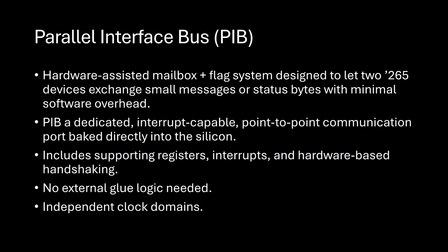Now with this, you should not need any external glue logic. You can have the 2 different microcontrollers on totally different clock sources, so independent clock domains. It's just a whole bunch of benefits to this. The idea of the hardware, though, is to make it really easy. You shouldn't have to do much coding. You should just be able to say, I want to store this byte of data, and the other microcontroller just gets it.